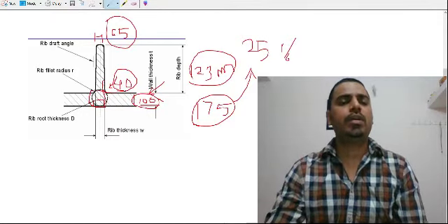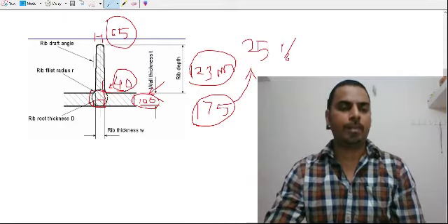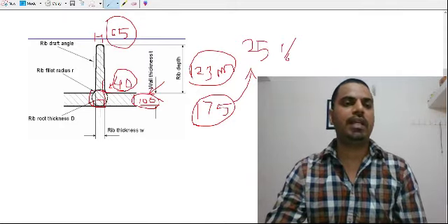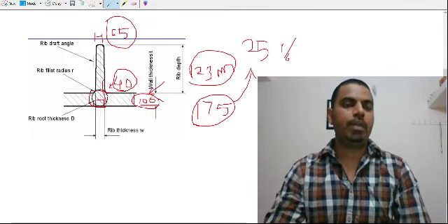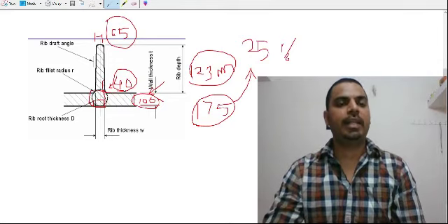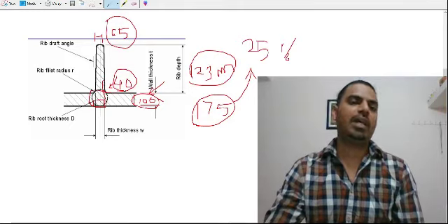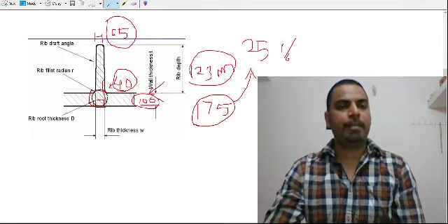Okay, one more thing in the design of a rib is that ribs are provided in the direction of draw. In order to simplify the ejection of a rib, we can provide a taper to the rib. If you increase the taper angle of a rib, then it might form a thinner section at the tip, which will again cause a problem for injection molding.